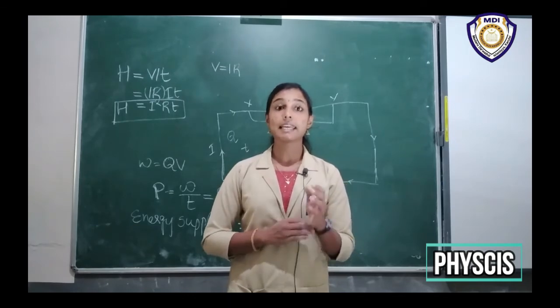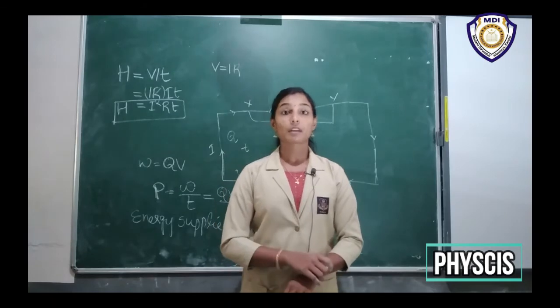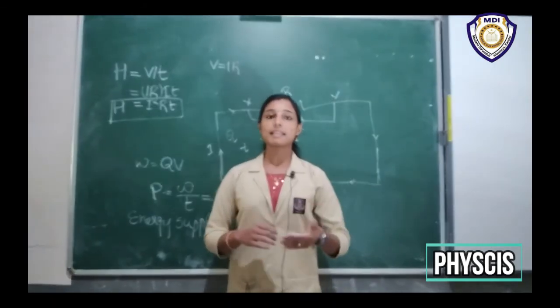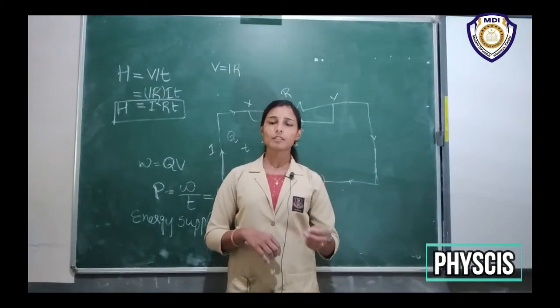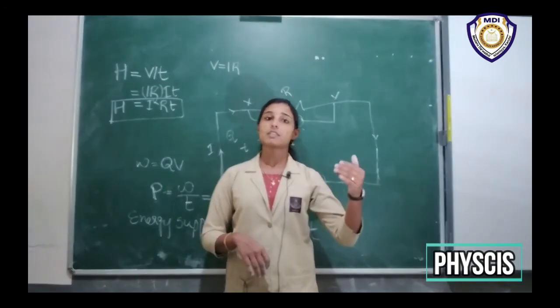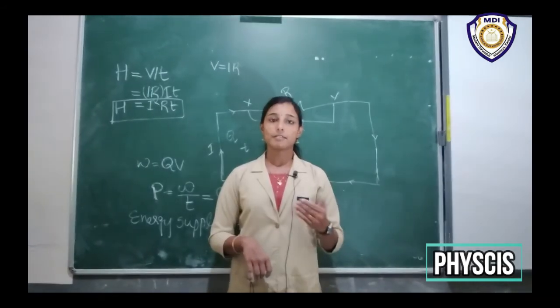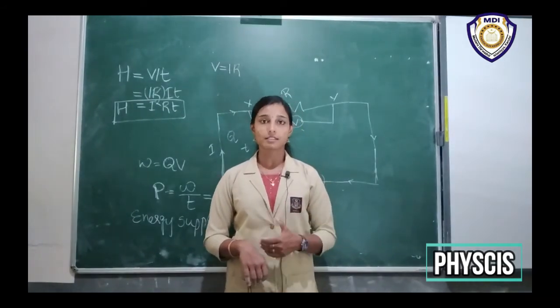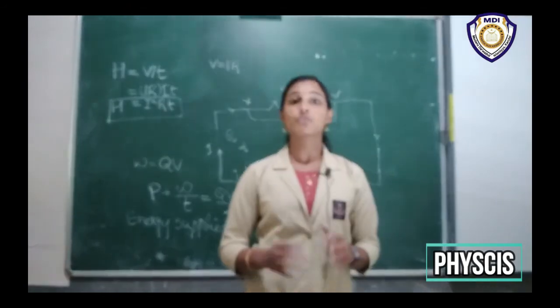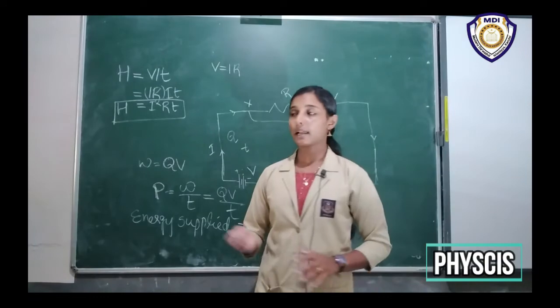That means the heating effect was there, and the wire inside that fuse burns due to this heating effect, the circuit cuts off, and that makes it safe for us. That is the use of a fuse, and how a fuse works with the help of this heating effect.